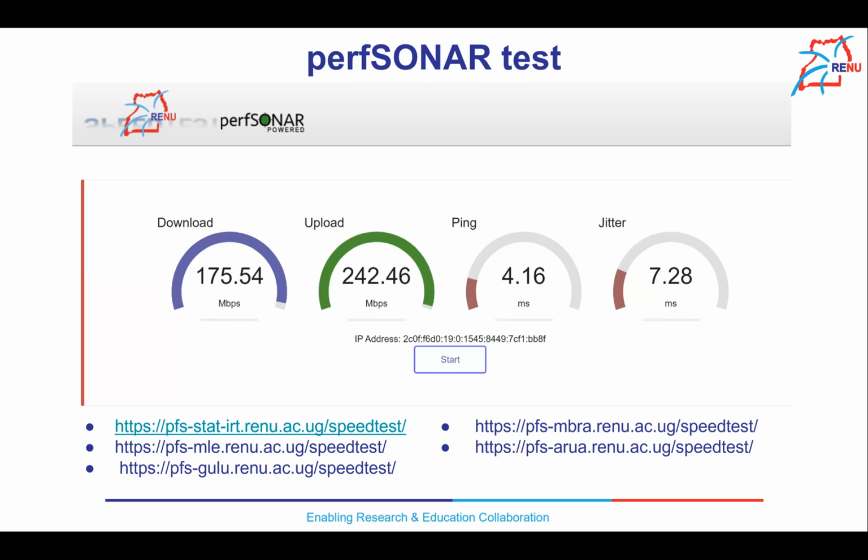Yes, why is the microwave backup not more trusted like the fiber cable? Do you want to take that, Ronald? Okay, so the question is about, actually people answered microwave is usually affected by weather. Fiber, of course, also has different effects, but there are two different technologies. And of course, fiber in most cases is better. If you look at the loss per kilometer of fiber, it is low compared to the loss any wireless signal might experience. Wireless signals can experience absorption, diffraction, refraction. Many things can actually obstruct your wireless signal if you're getting the microwave link.